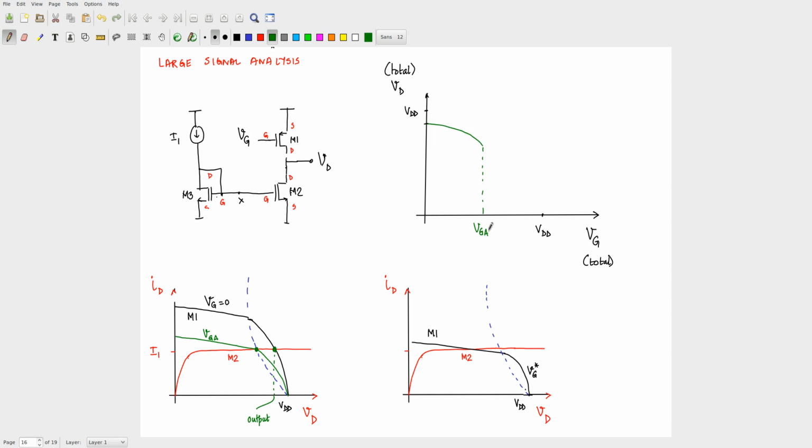Subsequently, what happens? Both devices are in saturation. So this slope of Vout to Vin, what's going to happen? Should it become gentler or steeper? Steeper, right? Because now you have both in saturation. To just see that, if you assume that both of these transistors actually have flat characteristics, how will that fall off be? It has to be vertical, right?